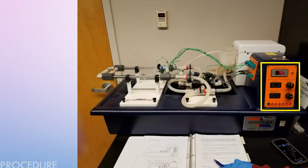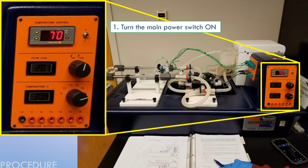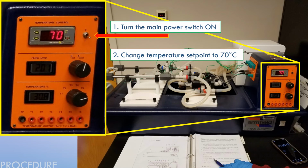This is the user interface that we'll be using to monitor the flows during our experiment. First, ensure that the power is turned on. Next, change the temperature set point to 70 degrees Celsius. This can be done by using the up and down arrow keys here.